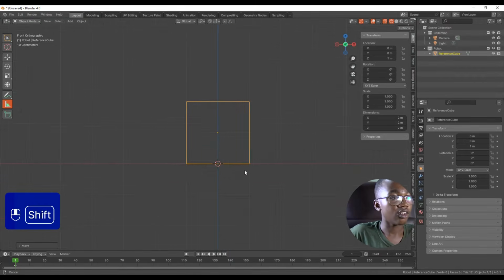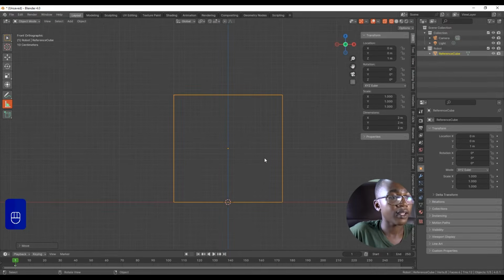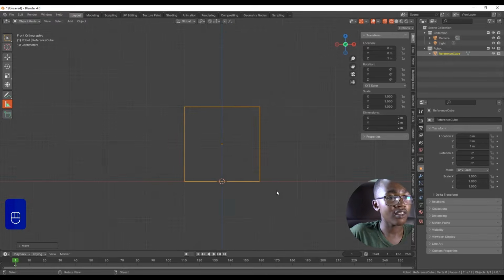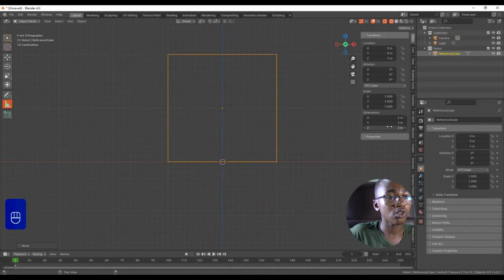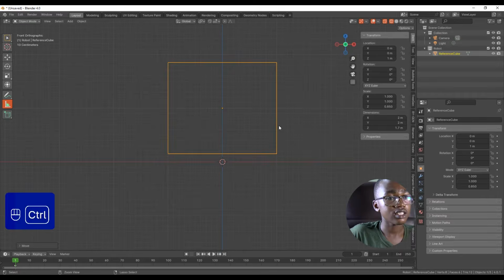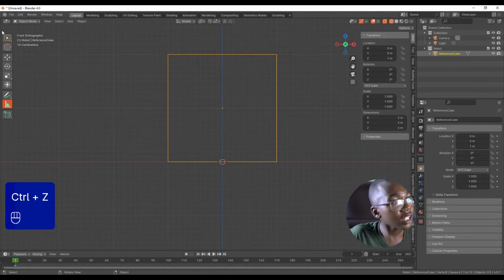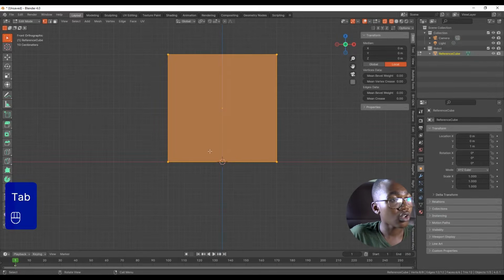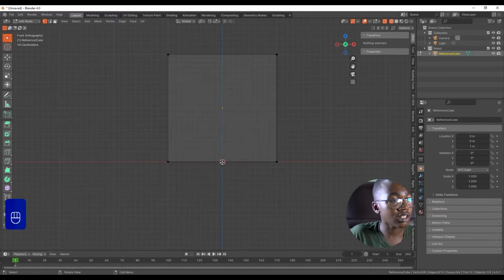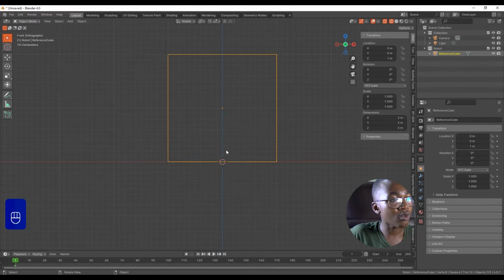Alright, okay, so let's go. So by default in Blender, the default cube is 2 meters tall, which is quite big in relation to what we want. So we'll reduce the size. First of all, to make that successful, we'll have to make the origin come down here. So how do we do that? By default, you can see the cursor is where we want it to be.